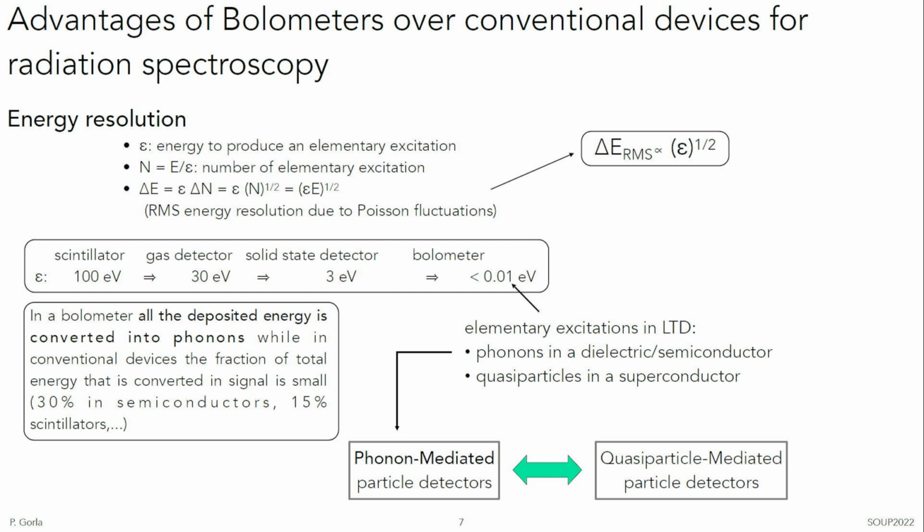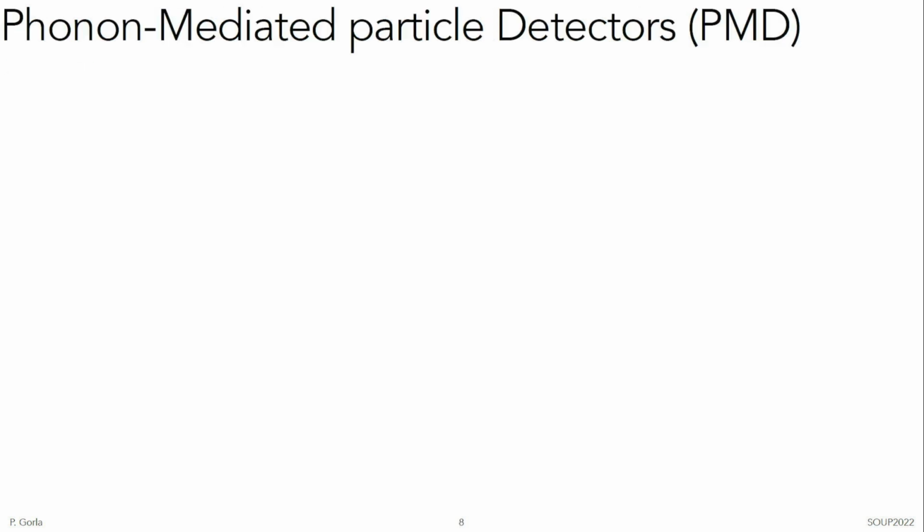This also tells you that the kinds of material which are best for this application are those with a very good crystalline lattice that allows very good propagation of phonons and easy detection. Amorphous materials are more difficult to use because the propagation of phonons is much less efficient, even though you can use this kind of material too.